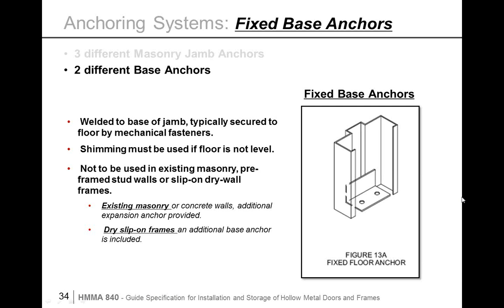Okay, there you go. The fixed base anchor is another anchor variation where there's no adjustment. It is welded to the back side of the jamb just like the adjustable anchor. And shimming occurs after the frame is in place and leveled.